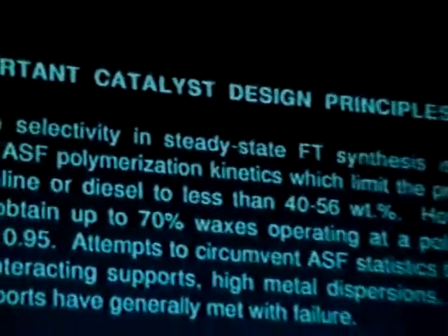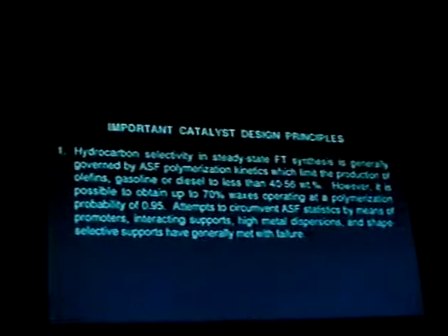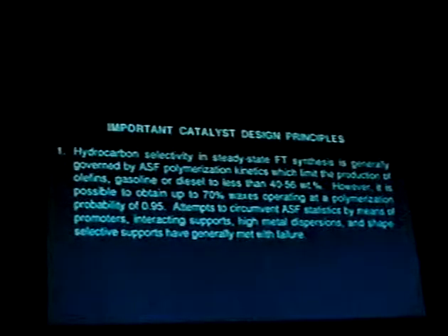Well, based on the examples which I've highlighted, and quite a number of other important studies that have been done in the last decade or so, I've listed 4 or 5 principles, well, let's say a half a dozen principles that are involved in catalyst design for Fischer-Tropsch. First, hydrocarbon selectivity in steady-state Fischer-Tropsch synthesis is generally governed by the Anderson-Schultz-Flory polymerization kinetics, which limit the production of olefins, gasoline, or diesel to less than 40 to 56%. However, it's possible to obtain 70% waxes by operating at a polymerization probability of 0.95.